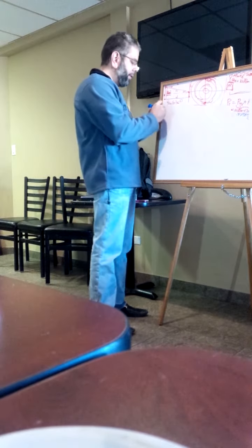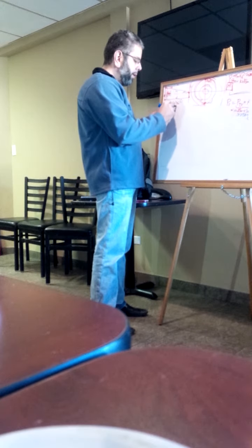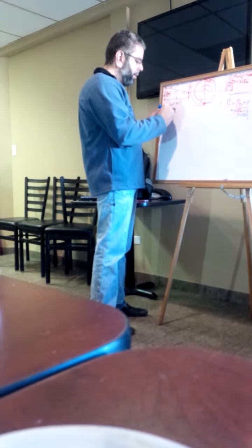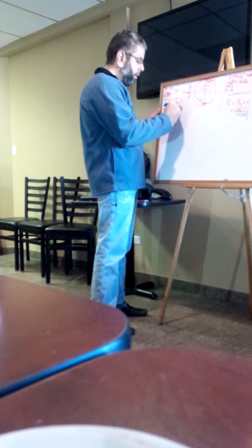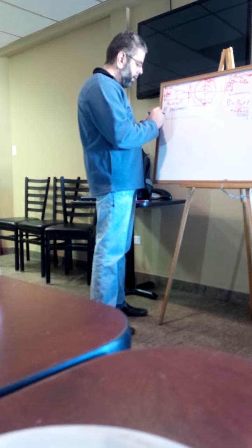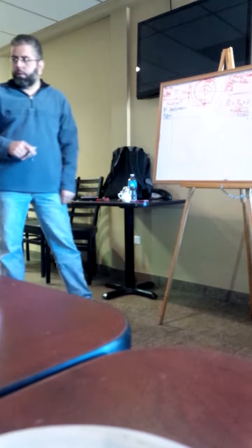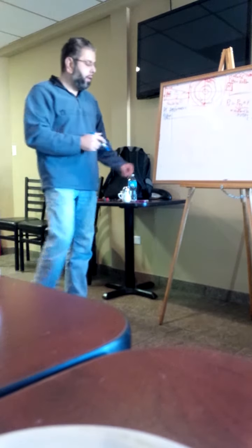So the RX performance I'm asking for is going to tell you something like this. This is the performance table that I'm telling you you should have. You will have something that says your RX power in dBm, and sometimes they call it RSSI, the received signal strength indicator.